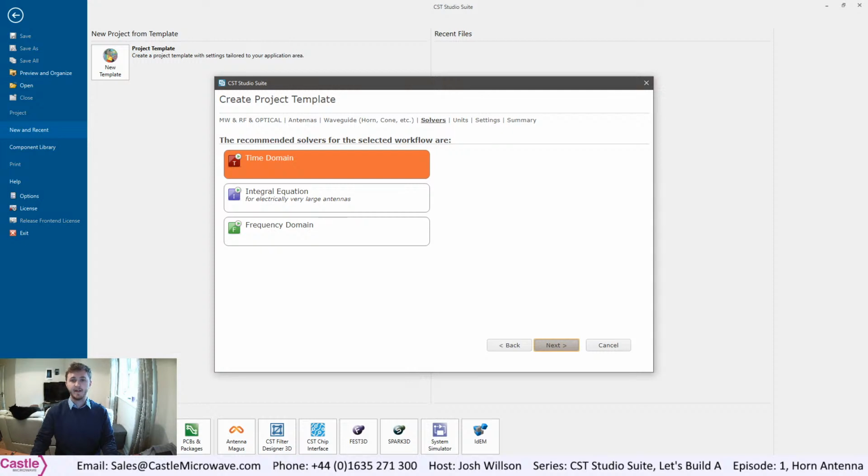The time domain solver calculates the development of fields through time at discrete locations and at discrete time samples. It calculates the transmissions of energy between various ports or other excitation sources and/or open space of the investigated structure. Consequently, a time domain solver is remarkably efficient for most high-frequency applications such as connectors, transmission lines, filters, antennas, etc., and contains the entire broadband frequency behaviour of the simulated device from a single calculation run.